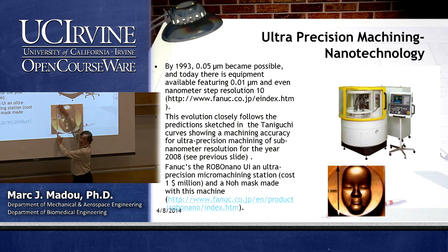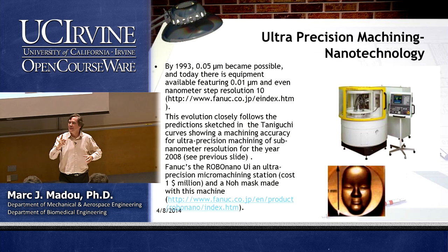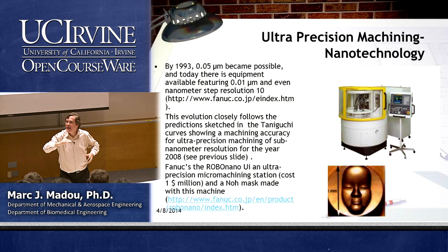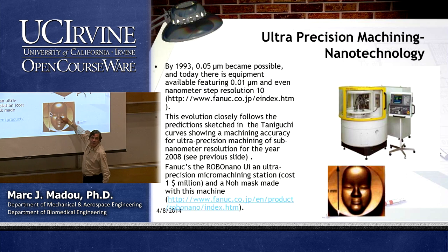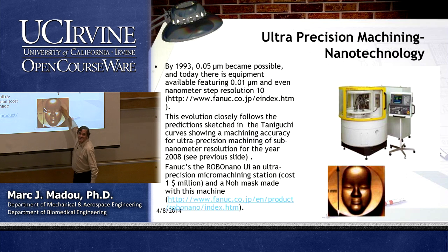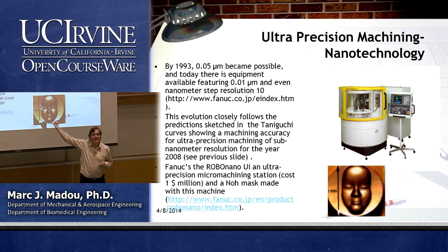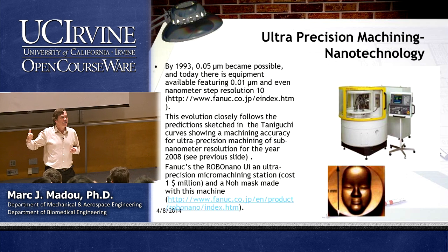This is 1 millimeter, so to cut this out, you cannot make the whole thing very small, but in one axis, you can make it extremely accurate. You can make very small dimensions possible. So this, to carve out the eyes and the nose, that's nanometer resolution. But in the other dimension, XY, you have to remain bigger. Why? Because of the tool size, remember? Maybe 22 micrometer. Do you get it now?